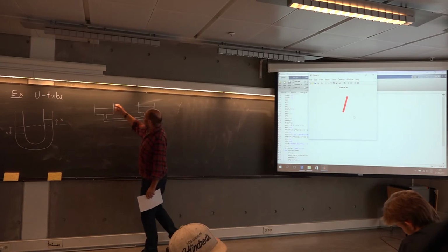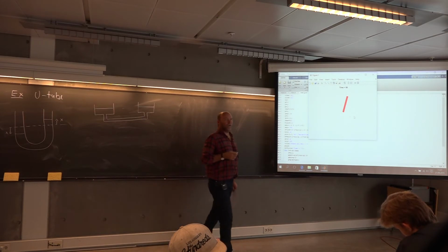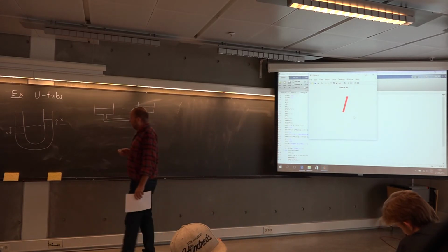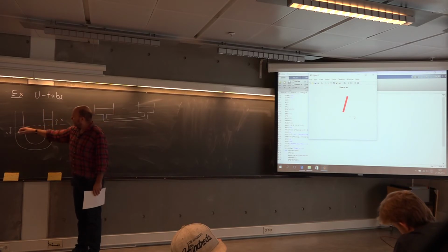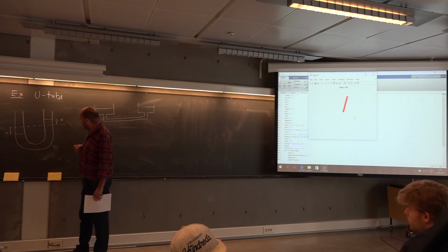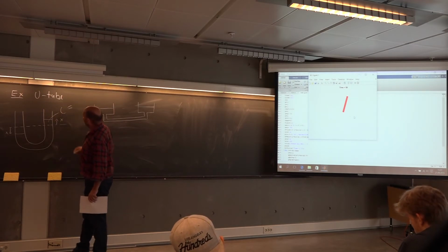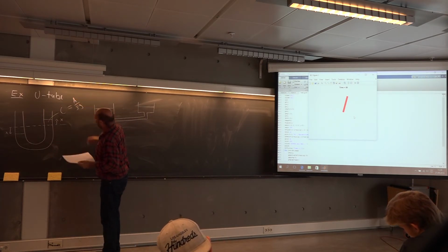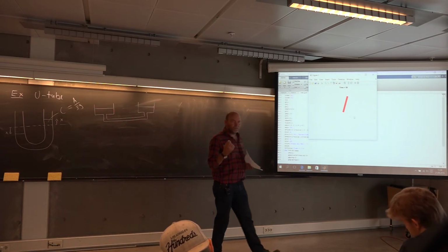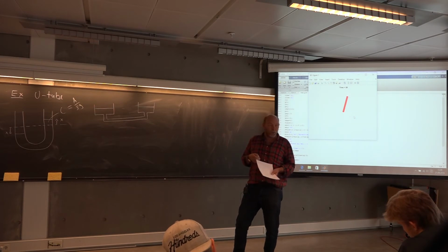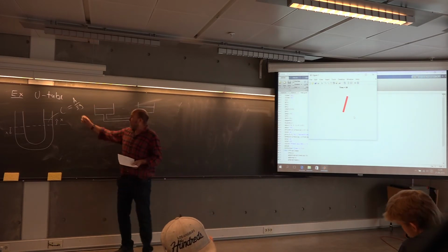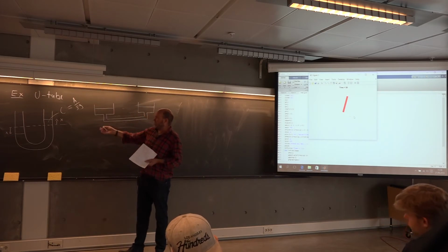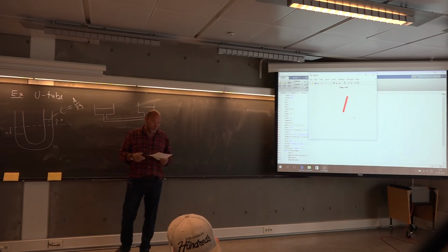So yes, you have a tank on each side, a liquid tank, which in the bond graph world is a compliance element. It's a C element. So here I just say I have two storage tanks, one on each side. Very simple. And what is a C element? That was the area, surface area, divided by density and gravity. So you might say the gravity is already present inside the spring element. So don't add the gravity twice by also thinking in terms of, oh, I need a source, I need a driving force in the problem. No, you don't. It's included in the spring already.